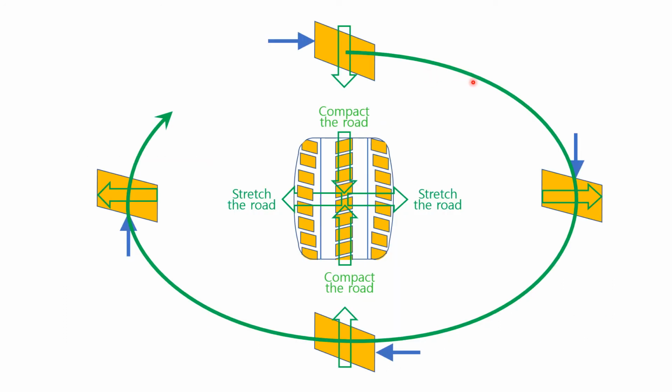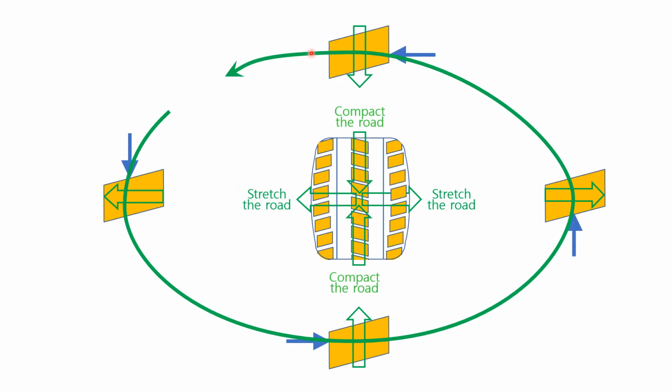This picture explains the mechanism producing plysteer. All the forces from the tread block make the tire rotate clockwise. If you change the shape of tread block to the shape of mirror symmetry, directions of reaction forces change to opposite. All the forces from the tread block make the tire rotate counterclockwise. You can change or eliminate plysteer using this principle. Therefore, tread block shape is very important to plysteer.